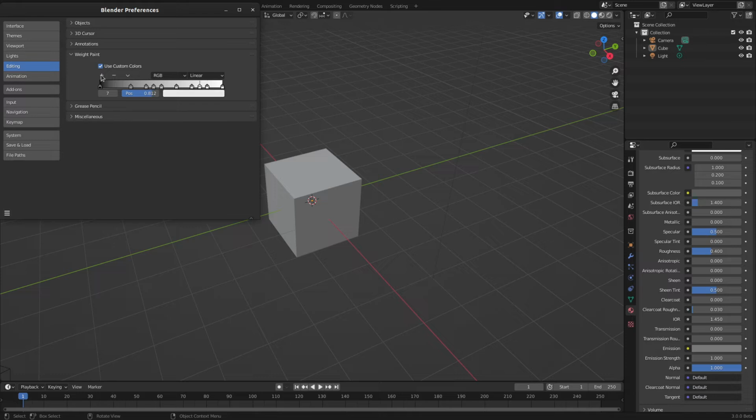Now you can just fill it up with control points. If you want to even them out, you go to your special menu, distribute stops from left. It will do leftmost distribution, or you can distribute them evenly, like so. If you want to remove a control point, whichever one is selected, you just hit the remove or minus button, and it will remove the ones that you don't want.